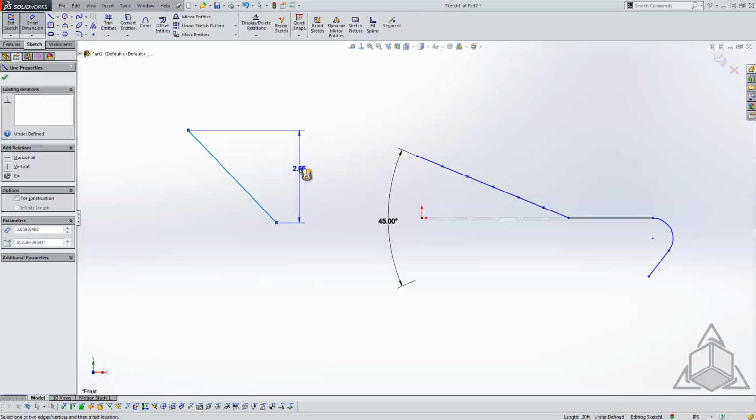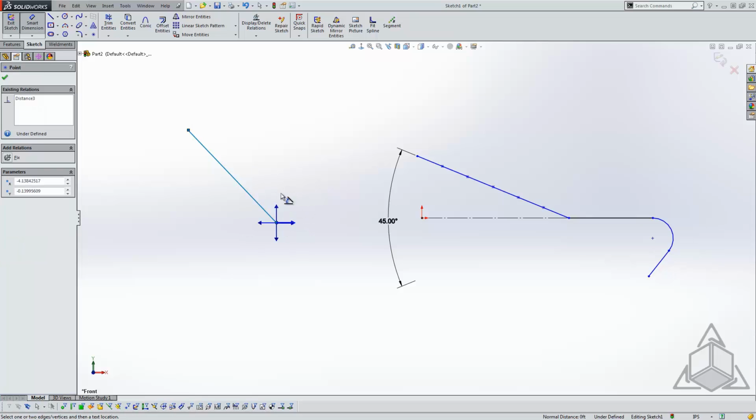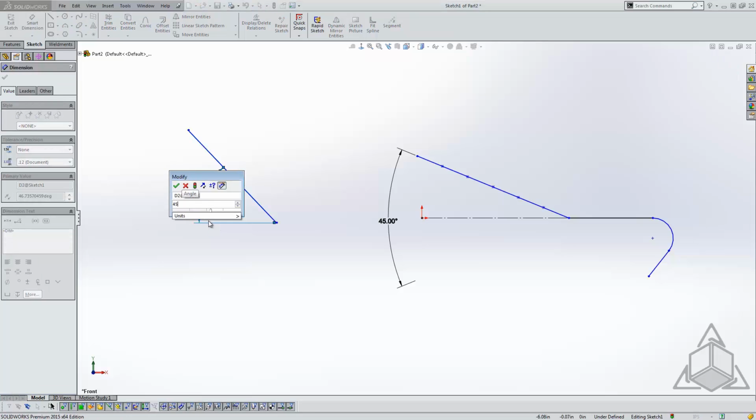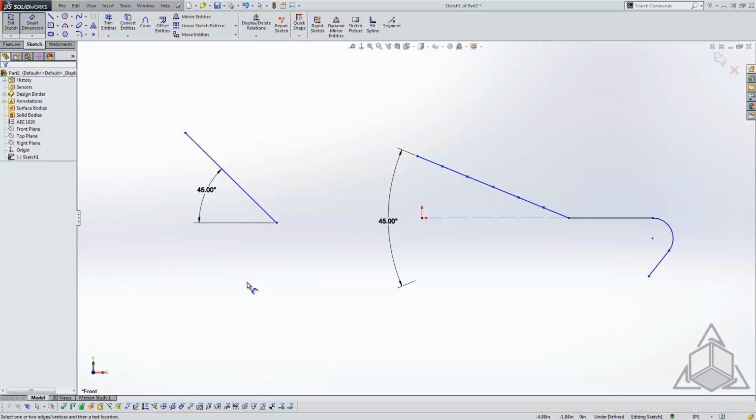But if we take a moment here, we can come back and select the endpoint of the line. So I selected the line, now the endpoint of the line, and what happens is it brings up this little set of arrows that's asking us where we want to dimension this angle from. And when I select one of these arrows, it then places that angular dimension. So this has come in really handy, and like I said, it's one of those tools that you don't see, so it's easy to forget. But once I've reminded myself a couple of times to use it, it's definitely saved me a bunch of time in dimensioning those types of things, where again we're saving ourselves from having to create extra reference, much like the way that this reduces time, this does as well. We're not having to create extra reference just for the sake of adding in a dimension. It's just immediately there for us. So definitely a cool option there.